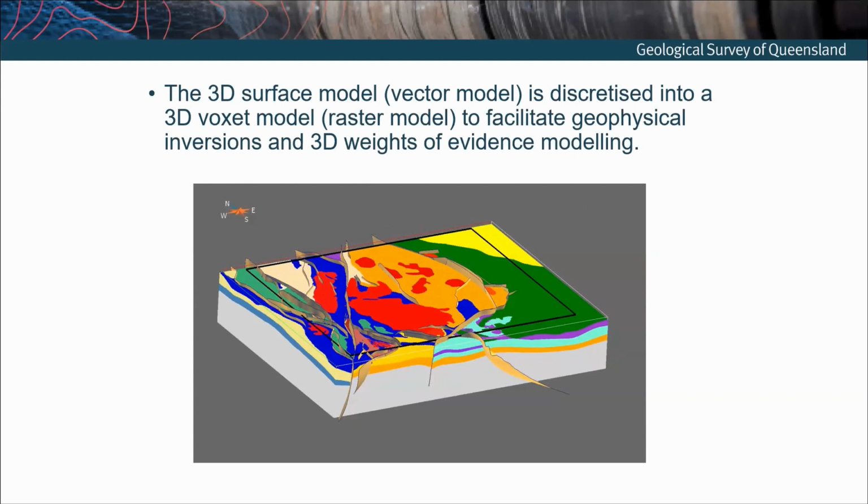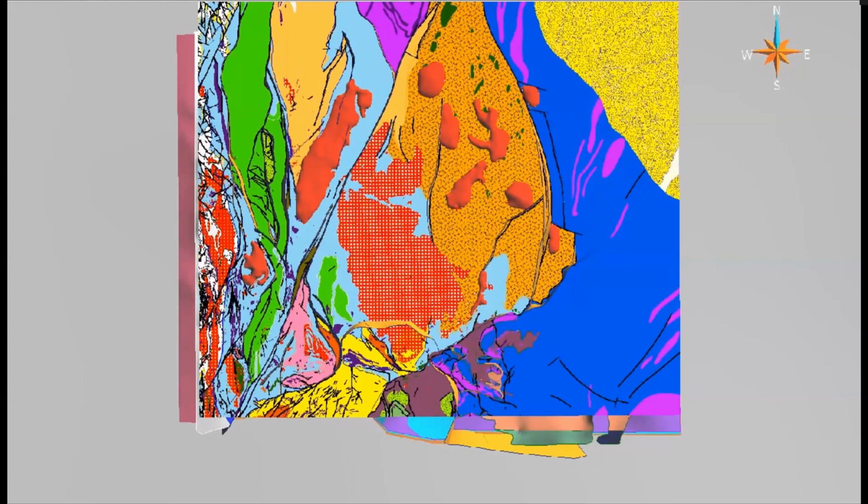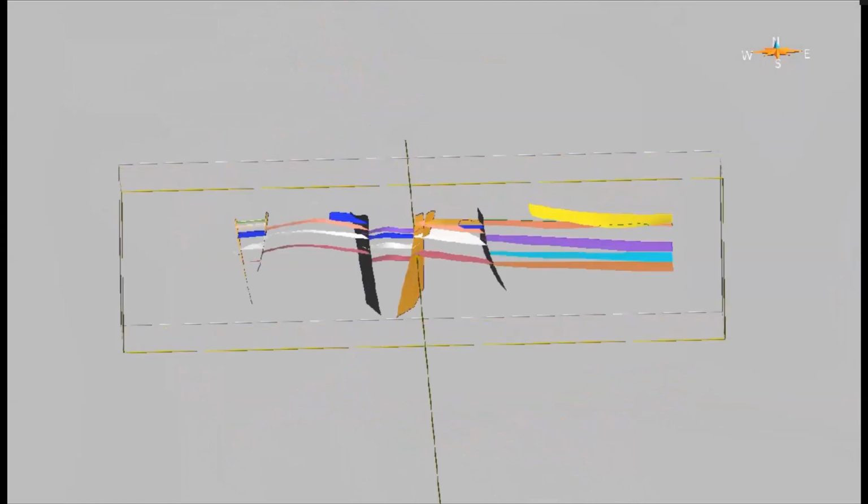properties. So now I have the first of my videos, which I hope is working, where you can see our surficial model there. And I'm going to slice into the surface model and then pull back through. And you can see we're trying to maintain that lithological contrast across there. These are the broad lithological packages we're capturing here rather than every particular unit mapped in the area. And then I'm going to convert that now into a voxel model. So now we have volumes that we can populate with physical properties.